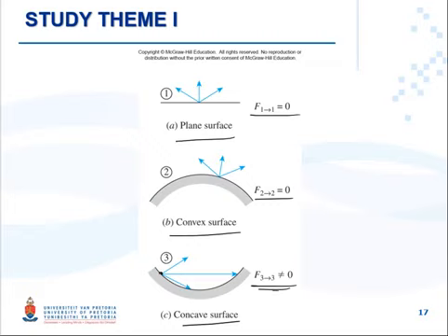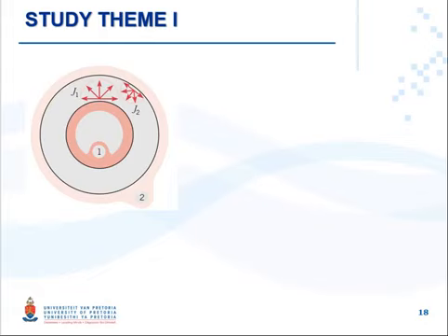Now we have two important general rules: we have reciprocity, we have summation, and we have a good understanding of self-view factors. Now let's try to solve one example and see how we can put everything together. This picture shows one enclosure formed by two concentric spheres. We want to find the view factors. How many view factors do we have here? 4 view factors, and we want to find them.